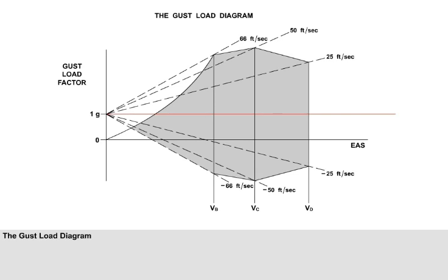In practice, a slightly higher speed than VB will be used when flying in turbulence. This speed is VRA, the rough airspeed. VRA will give protection from both overstressing the structure and an inadvertent stall, and will be examined later. Please make a note of which design gust value is associated with each design speed. The examiners may ask you.